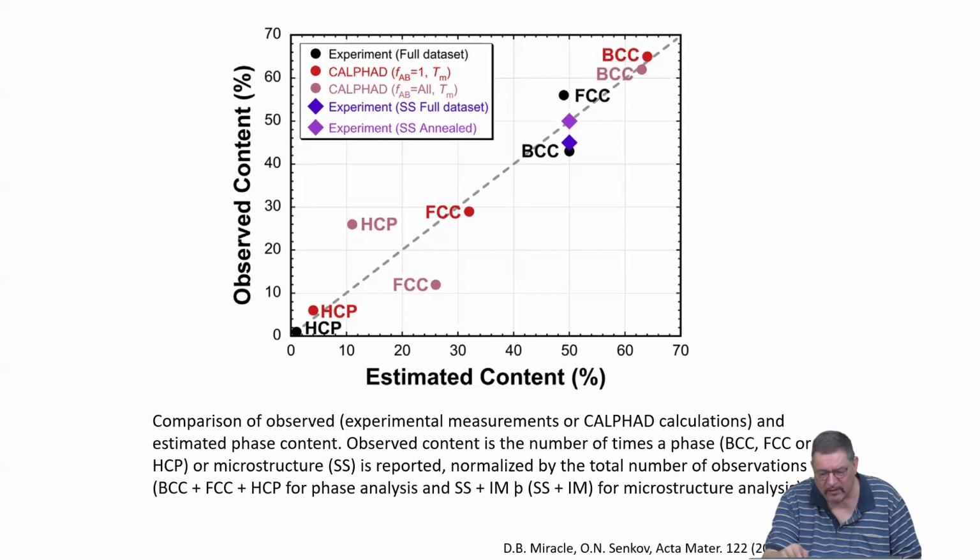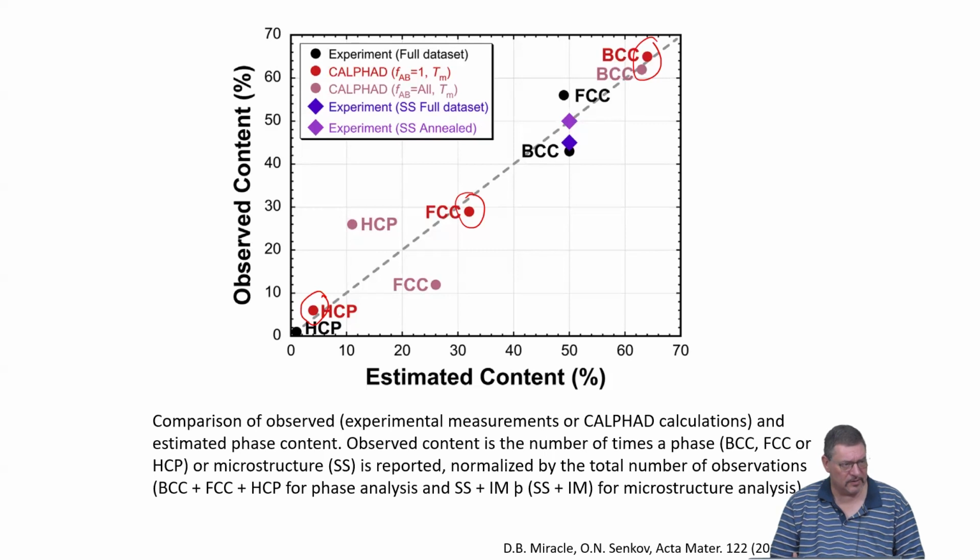And you see that obviously the fully assessed ones are the ones which are better, because then you really can predict, and Calphad is working great, so you can rely on the outcome of Calphad calculations, as you can nicely see when you compare these here. But if not all of the binaries have been assessed, then obviously there are larger deviations possible. All in all, the structure in, structure out approach works.